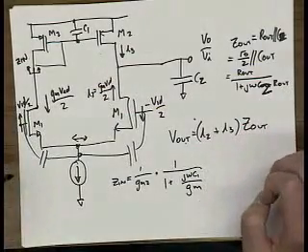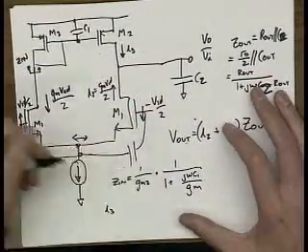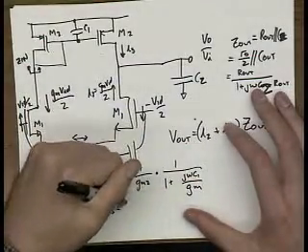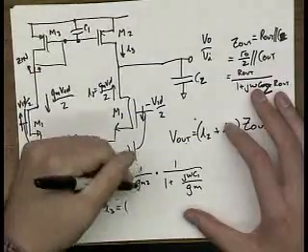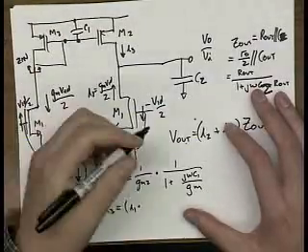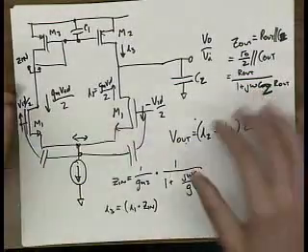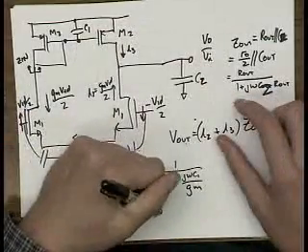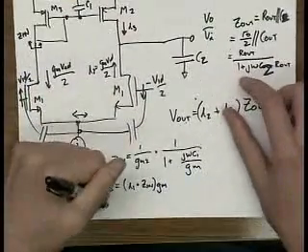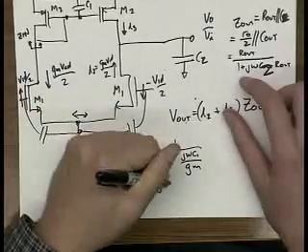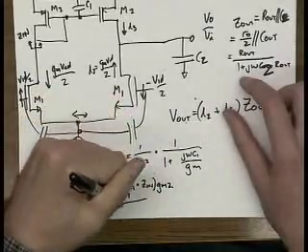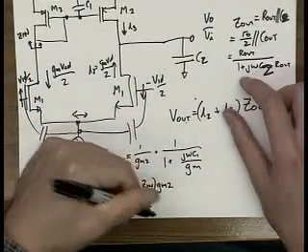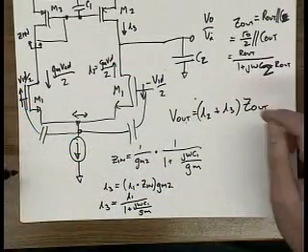And we know that I3 is equal to the voltage on this node. The voltage on this node is going to be I1 times Zn. That's the voltage that gets translated to this node, and then that just gets translated out through the transconductor, Gm. So I3 is I1 times 1 over 1 plus j omega C1 over Gm. Everyone see that?